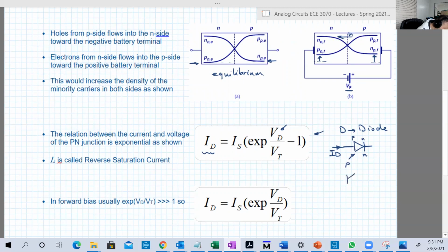If we draw it in another way, you can draw it in whatever way you want, direct or vertical, that's fine. So the current is again from P to N. And like any other element except the battery, the voltage drop is in the opposite direction of the current. So ID is in that direction, and VD is just opposite to that. Again, if you draw it with P here and N here, ID is flowing in that way, and VD is in that way, from N to P.